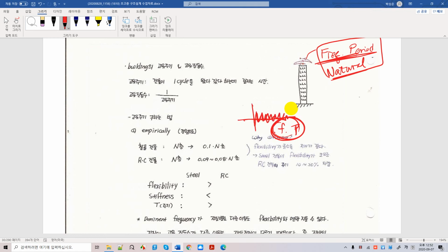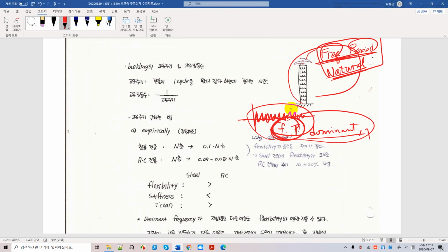And here, the frequencies and period from earthquakes are referred to as dominant. Most earthquakes have a dominant period and dominant frequencies. So these are what affect the building behavior. And the building will have its own natural frequencies and period. So don't get confused. We have one over here, we have one over here. Now we're studying the period and frequencies of the building in these sections.